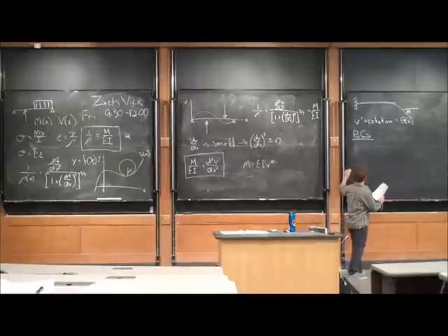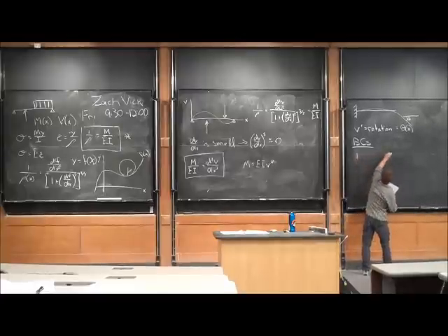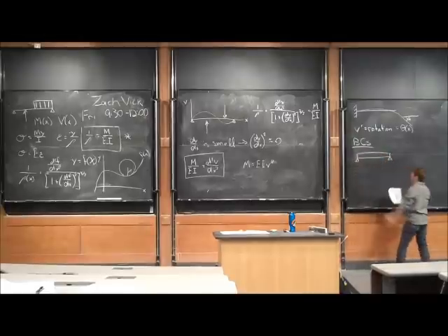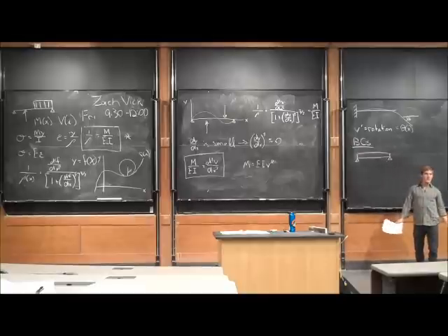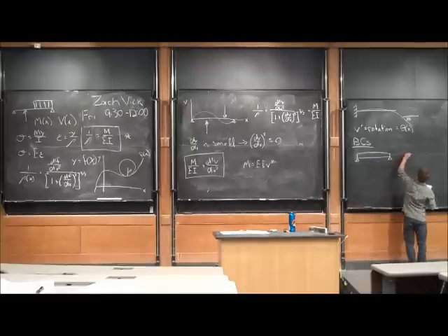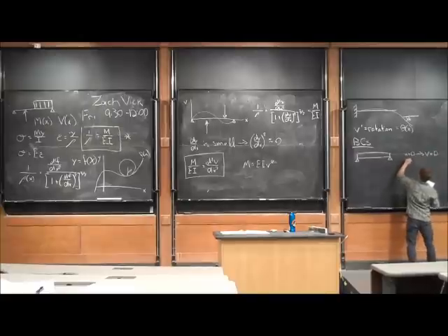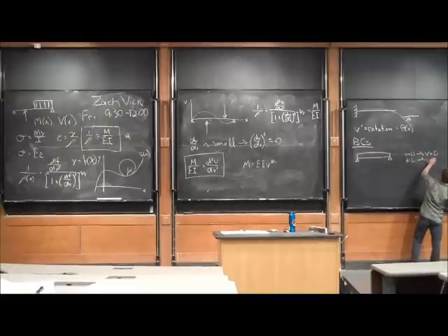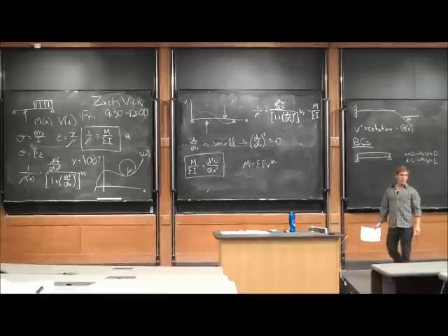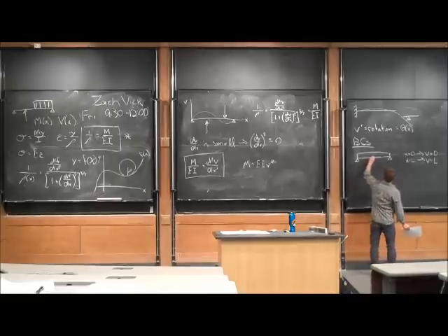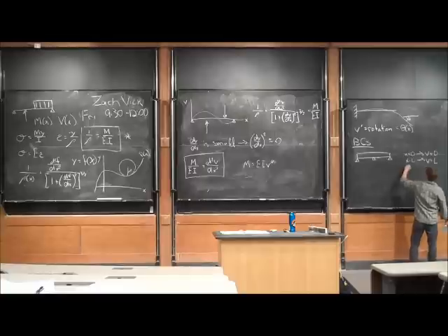So let's just give some examples. If we have a beam with pinned ends, what is going to be the deflection at the pinned location? It's going to be 0. So our boundary conditions in this particular case are that at x = 0, the deflection is equal to 0. At x = L, the deflection is going to be equal to 0. Does that make sense? Everyone follow me? That's not always true for any location. If we had an additional pin joint at the middle, we'd also have at x = L/2 the deflection equal to 0.